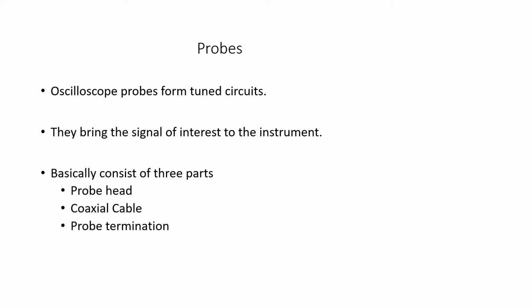It is used in order to avoid undesirable loading effects of the shielded probe. Next is the high voltage probe, also known as voltage multiplier probe, which can apply voltages of the order of kilovolts to the CRO. It is essentially a potential divider. The voltage to be measured is usually divided by a factor of 1000. In this probe head and probe tip, well insulated plastic or thermoplastic material is used to protect the user from shock.